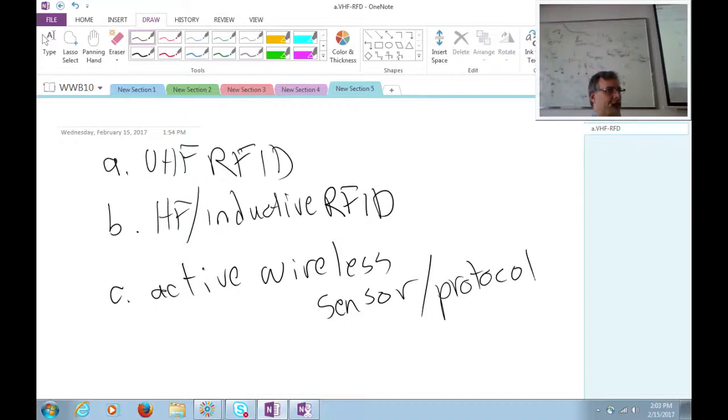Yeah, either of them. If I had to rank them based on the specs that I've given, it has to work in your pocket. So keep in mind that's close to the human skin. You'll see that makes things very difficult in terms of antennas. You'll easily lose 10 dB or more operating close to the skin. So even though if this tag was floating in free space, you could probably use A, right? But that's a little dicey. So I think I would probably prefer, like you said, C.